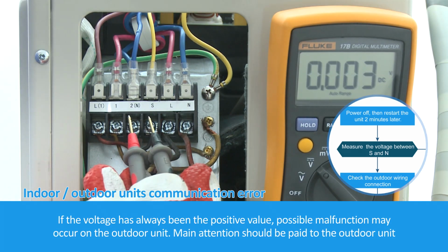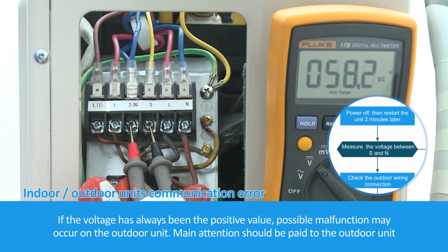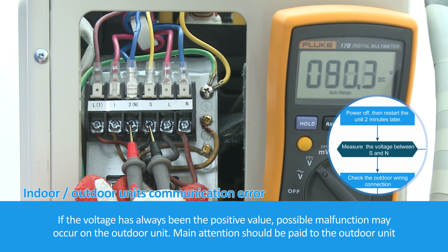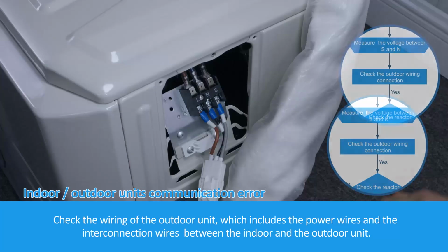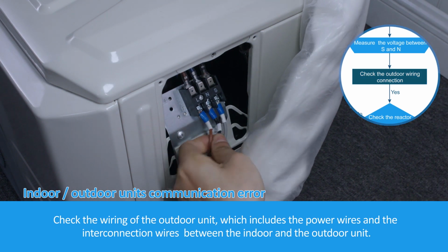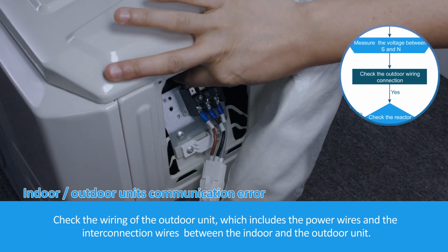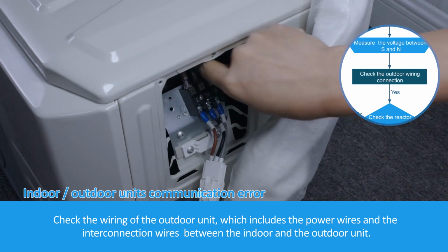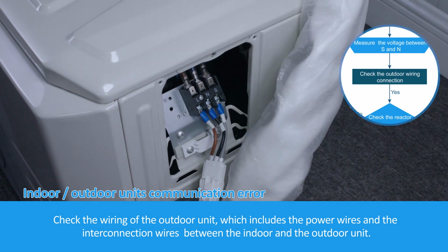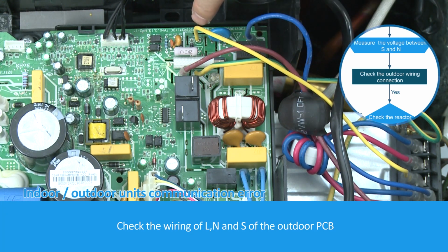If the voltage has always been the positive value, possible malfunction may occur on the outdoor unit. Main attention should be paid to the outdoor unit. Check the wiring of the outdoor unit, which includes the power wires and the interconnection wires between the indoor and the outdoor unit. Check the wiring of L, N and S of the outdoor PCB.